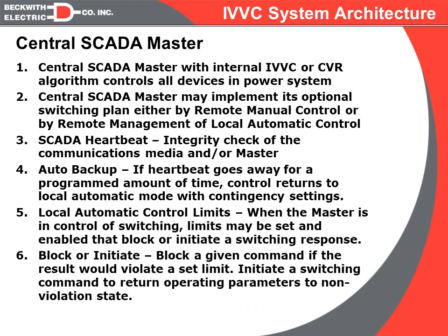So, with that in mind, we still want to have some capabilities in that local control for two reasons. Number one, for backup. If we lose the heartbeat, we need to be able to regulate the voltage by closing in cap banks or raising and lowering tap positions. So if SCADA is down, we still need to have some sort of local operation to fall back to.